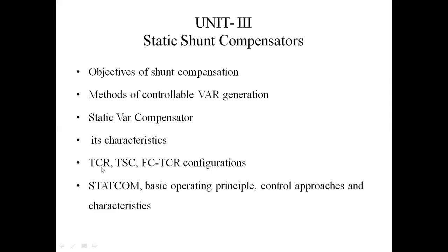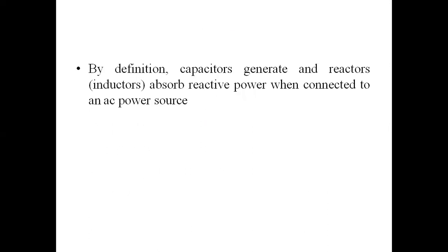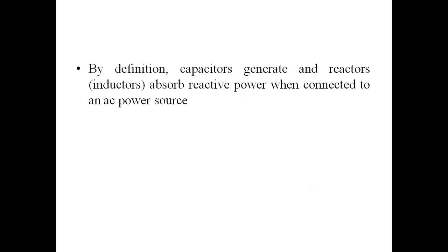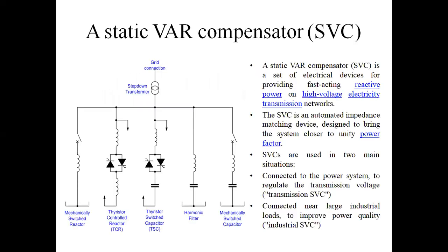TCR means thyristor-controlled reactor. This is the basic definition of SVC. By definition, capacitors generate and reactors absorb reactive power when connected to the AC supply. Reactors means inductors. This is the static shunt compensator or SVC definition. This is the SVC structure, static VAR compensator, shortcut form SVC.